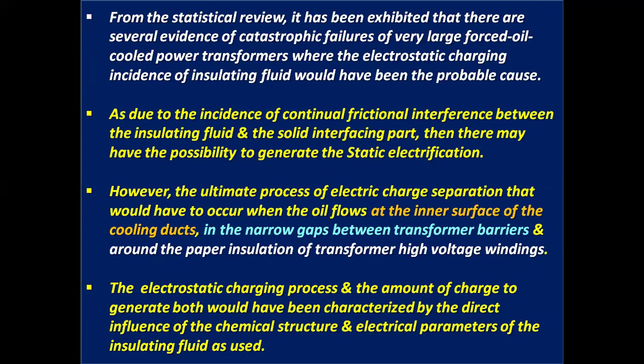From the statistical review, there is evidence of several catastrophic failures of very large forced oil cooled power transformers where the electrostatic charging of insulating fluid would have been the probable cause.